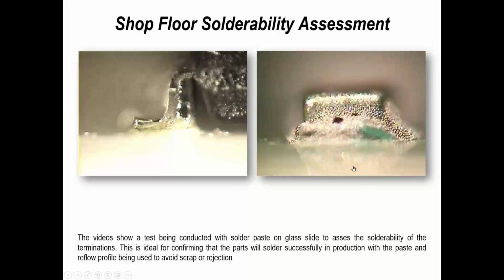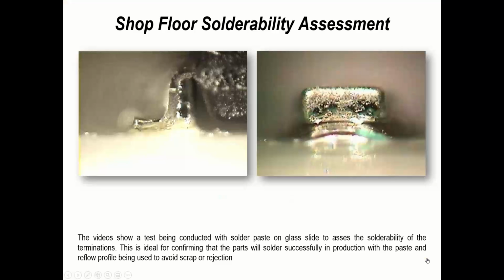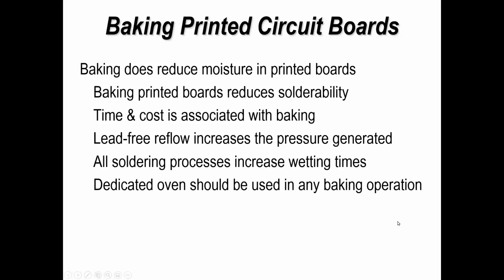no problems at all. If you look at these chip components, it's quite clear that there is a little bit of wetting to the surface of the chip termination, but the component actually lifted on the solder paste during reflow when it was wetting, and we've got something that's sitting proud. And that's on both ends, by the way. You might think it's just popped up like a drawbridge or a Manhattan skyline or a crocodile, but it was lifted on both ends. And these are samples that we were using as part of an evaluation. So on the component side and on the board side.